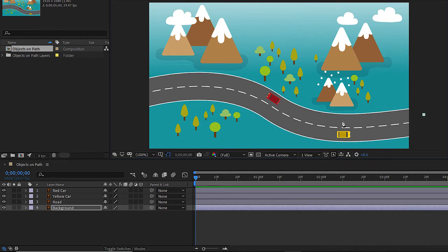Then I'll go right about here in the low point of the curve and click and drag, holding the mouse down to get control handles. Now, I want to use as few points as possible to make this as smooth as possible with the different turns. So I'll go up to the top part of the next curve and click and drag to draw out really long handles here. And then I'll go way far off the left side here and just click once to add another point. Now, clearly we need to adjust this path.